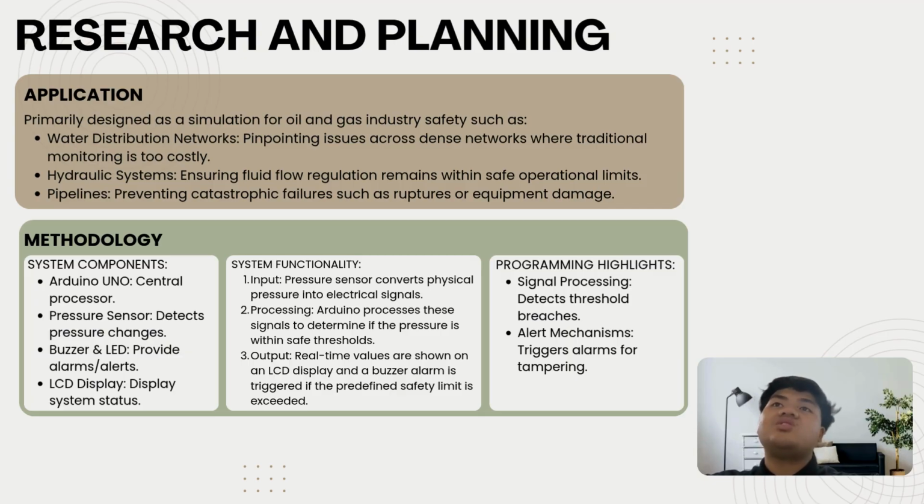Next is system functionality. First, input: the pressure sensor converts physical pressure into electrical signals. Second, processing: the Arduino processes these signals to determine if the pressure is within the safe threshold. Third, output: real-time values are shown on an LCD display and a buzzer alarm is triggered if the predefined safety limit is exceeded.